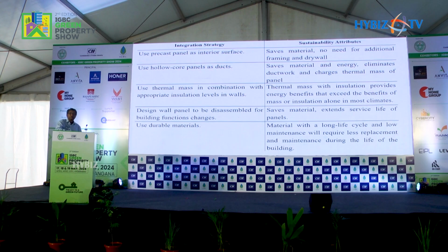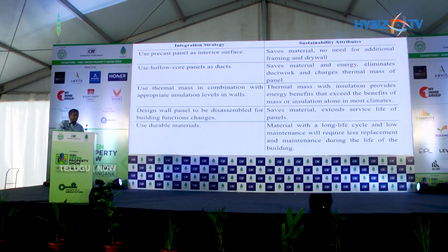Hollow core panels, we use them as ducts. Precast panel as interior surface. Thermal mass in combination with appropriate insulation levels in the wall. Design wall panels to be dismantled for building function changes. Yes, it can be done. And durable materials. Some of the sustainable attributes are there, saving on the material and other things.